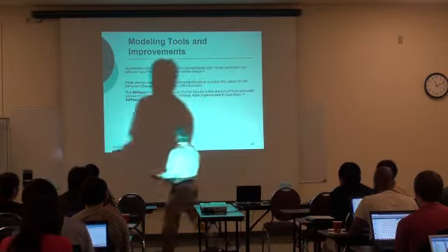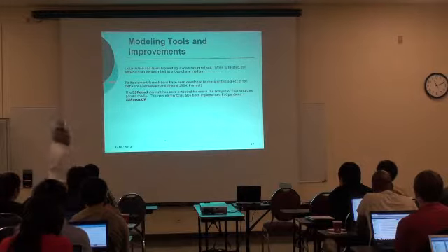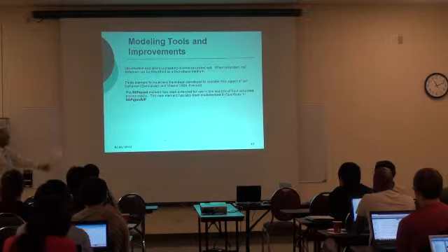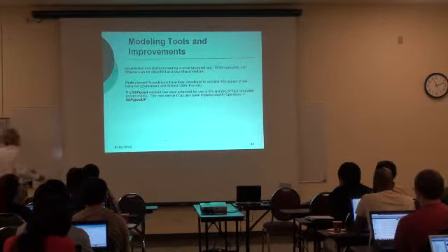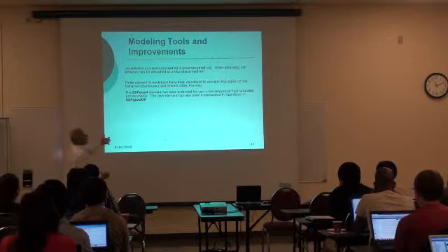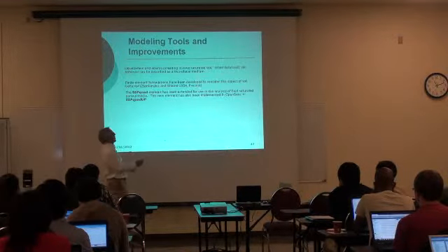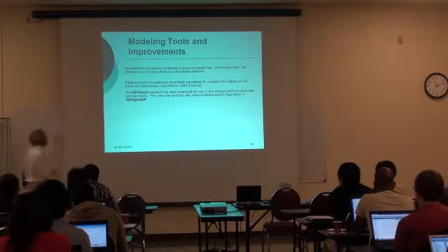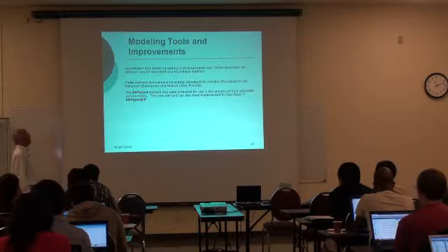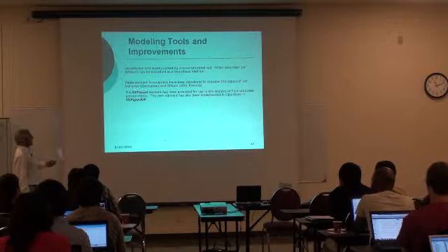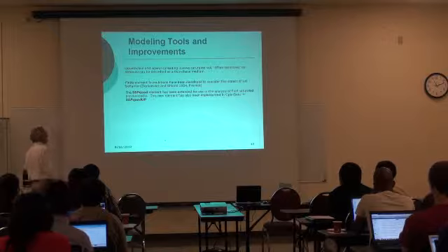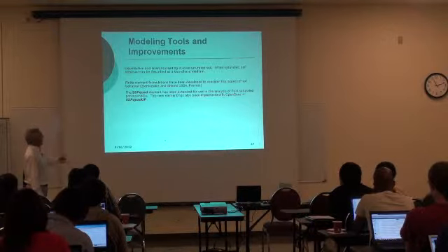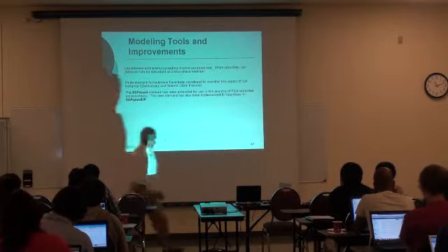Now, when you try to do a liquefaction analysis, you now have to include the water, and as I mentioned, we can use these fully coupled formulations, in particular the work by Zienkiewicz, which is cited everywhere. So what we did was extend the SSP quad in order to include a fluid saturated porous media condition, and we developed the SSP quad UP.